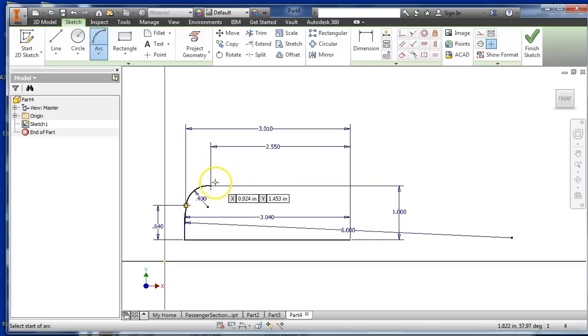And lastly, from here down to the right side of this horizontal line, and this also has a radius 6 and it's bowing out or up. So I click there, I get it to bow in the correct direction, and I now use my keyboard to type in the correct radius, 6.0. Right click and say OK. Okay, so we've just done that. I'm on to part 2.